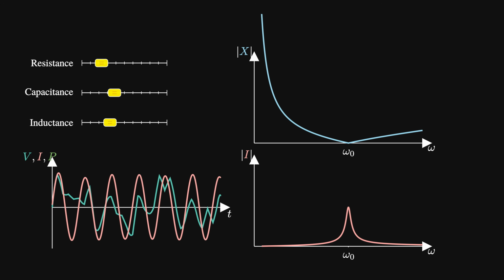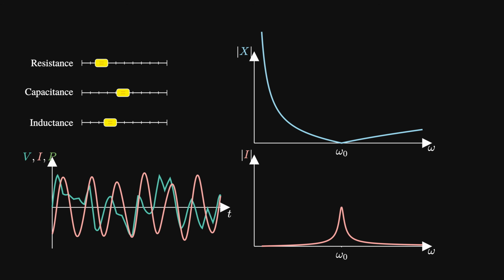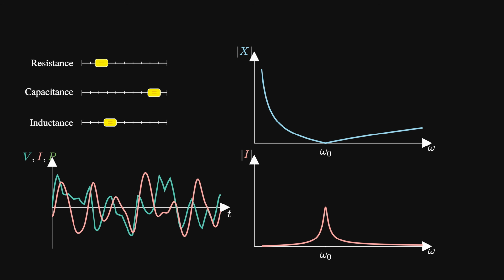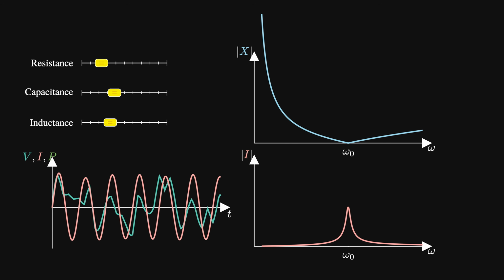In a radio, the dial usually controls the capacitance of the circuit, because changing capacitance allows us to change the resonant frequency and nothing else. It does this by simply varying the plate distance between the capacitor, if you are curious.